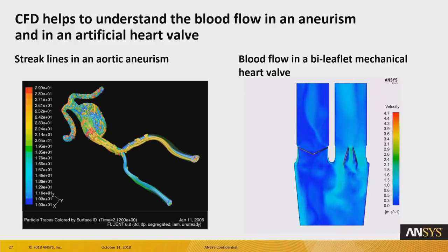Once it calculates the stress and motion, the displacements of each leaflet are propagated back from Mechanical to Fluent. Fluent then deforms the mesh based on the leaflet displacements and then continues calculating the field until the solution converges. And this happens over again at every time step.